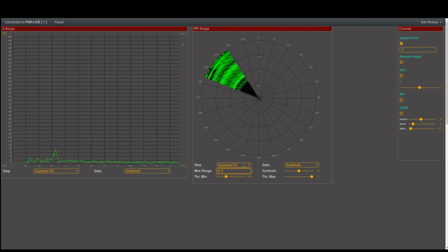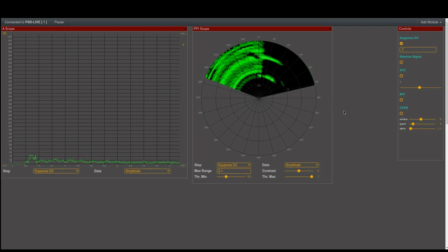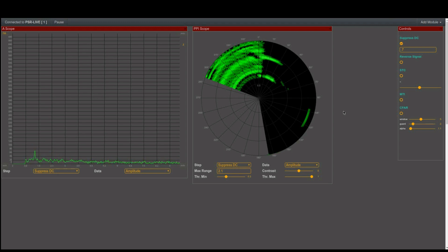The radar is of course trying to take the whole scope from 0 to maximum for the signals that it has, for the reflections that it sees. And here it's just fully amplifying noise because it hasn't seen any strong reflections yet. Now the first reflections come from our metal lab. So the computer screen should be very strong. There, the complete computer screen is a very strong reflection. That now becomes a reference. You see, everything happens in parallel in the A-scope. Always look at both.